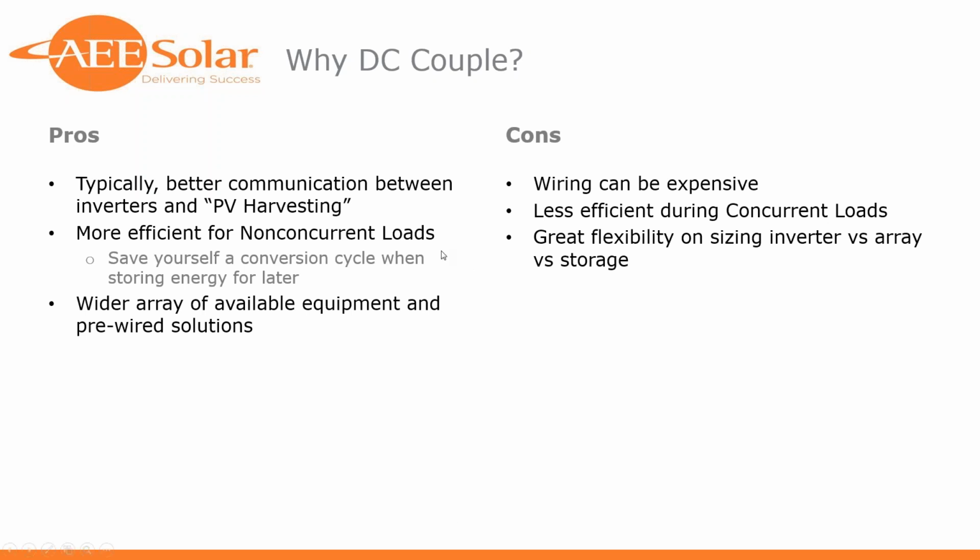I'll say more efficient for non-concurrent loads. So we'll talk about this in a few slides, but I think this is a key point. When you're storing energy for later, you're saving yourself a conversion cycle. And I've got some diagrams. We'll get into that a little bit later. The last point here in pros is simply a wider array, pun intended, of available equipment and pre-wired solutions. So simply put, more product to choose from to meet this application.